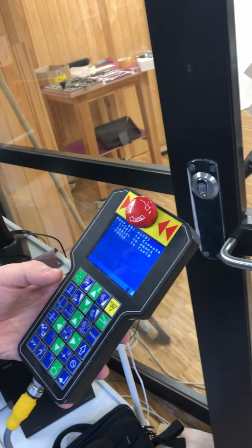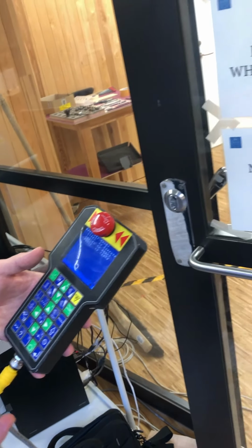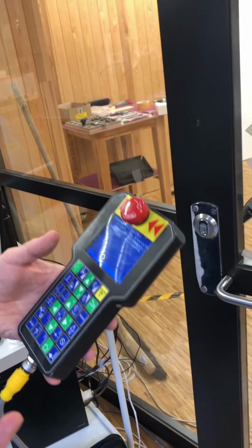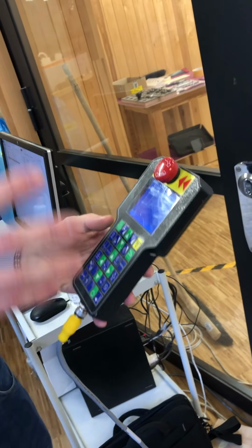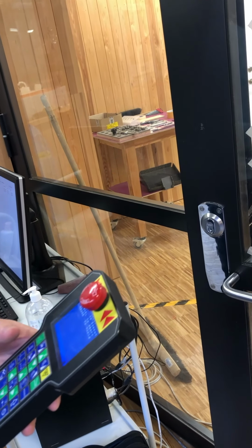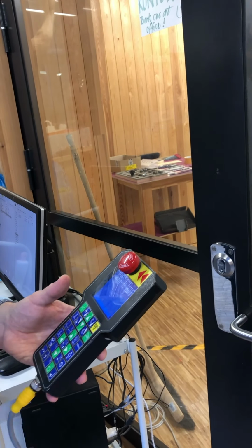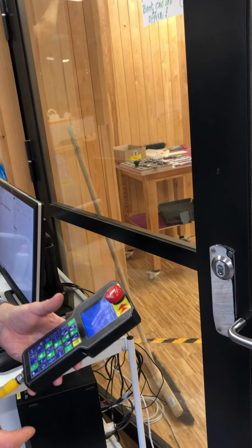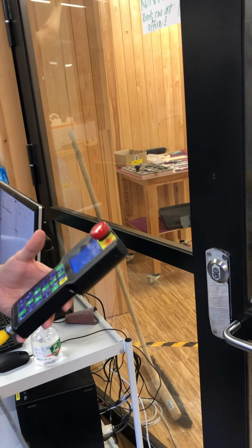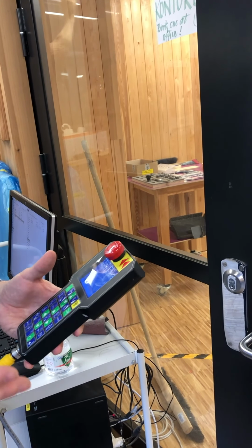One thing to just reiterate or remind you of is that the one thing that is actually essential for the quality of the cut, it's not the feed rate only, it's not the speed only, it's those two combined which defines the chip load per tooth. How much material each flute actually has to cut through. If that gets too much, then the whole machine will have trouble moving through the material, and that's really not good. If it's too little,